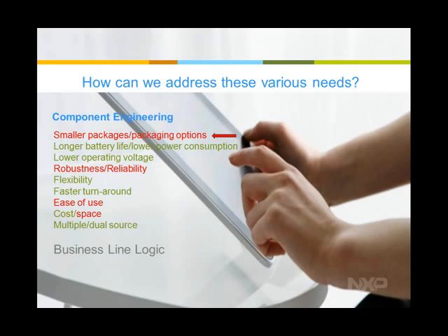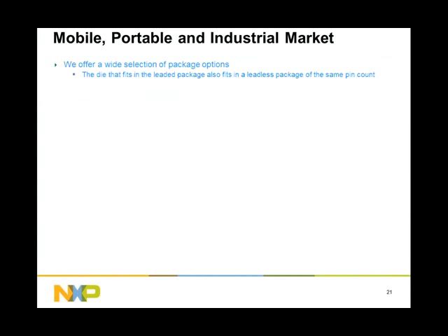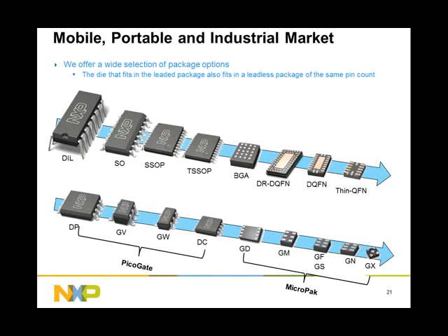So focusing for a moment on packaging options, we offer a wide selection of package options. And the thing that's important to note here is that the die that fits in a leaded package also fits in a leadless package of the same pin count. So for all of these products here on the top row, the die that fits in the DIL package on the extreme left also fits in the thin QFN package on the right.